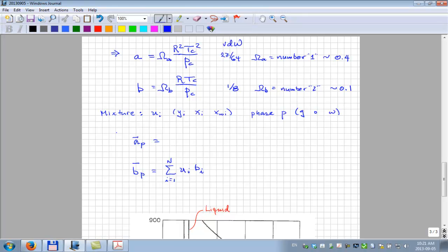For the average A, for reasons I can't even explain to you, I mean, smart thermodynamicists can, and van der Waals certainly could if he wasn't six feet under, you use what's called a quadratic mixing rule in order to be thermodynamically kosher, to get the best results from a thermodynamics point of view.